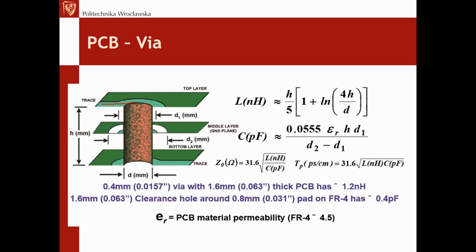But the construction is actually the same. From a technological point of view, a hole is drilled, and then chemically a metallization is made, which is a connection between the layers. So we have actually a copper connection between the layers. This seems very strong, and this seems very high quality.